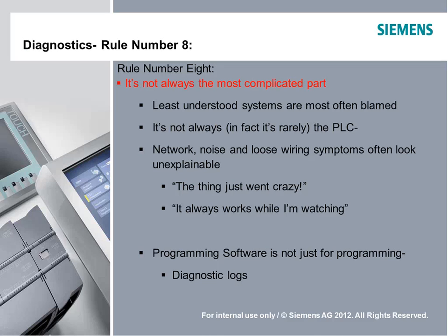It's actually something peripheral to that, especially if we're talking about PLCs. And the reason being, PLCs these days have what's called an MTBF, or a mean time between failure, that's measured in decades. So the chances that the PLC itself went out, pretty slim, at least in comparison to some of the possibilities that some of the other issues would be causing the fault.